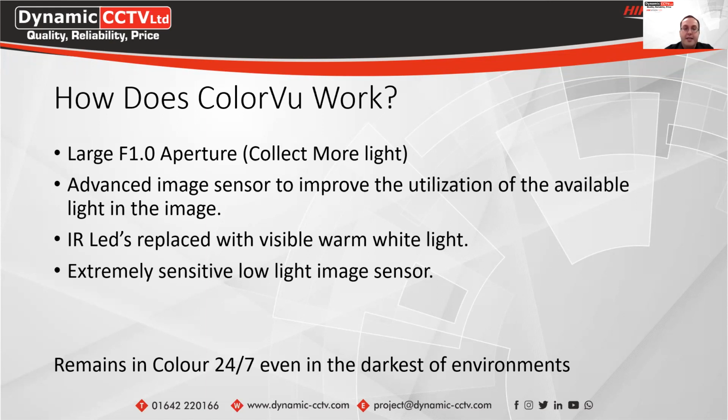The IR LEDs in the cameras are replaced with visible warm light LEDs. So there's no IR at all on the cameras, they are full white light cameras. And the image sensor itself is designed for extremely low light environments. With this all in conjunction, you can keep the ColorVu camera in color 24/7, even if there isn't any ambient light in the area or it isn't enough ambient light. You can use the white light LEDs of the camera to give you that light source to keep the images in color all the time for your customers.